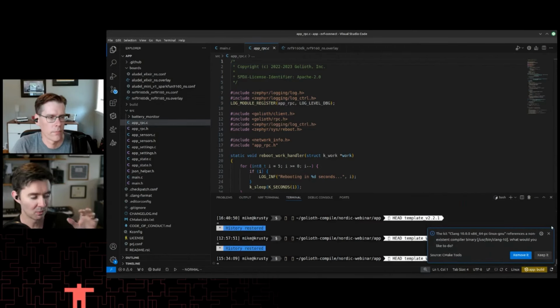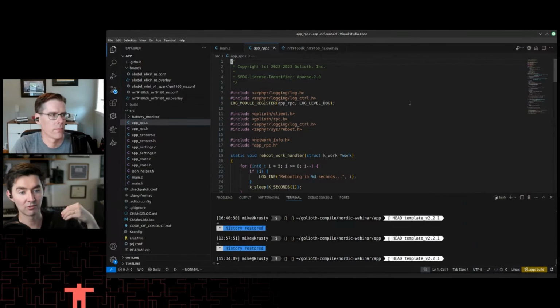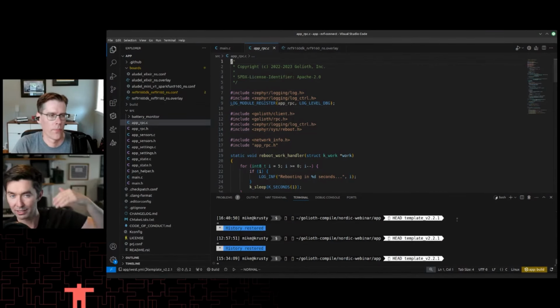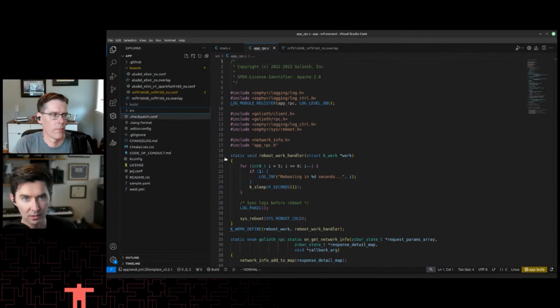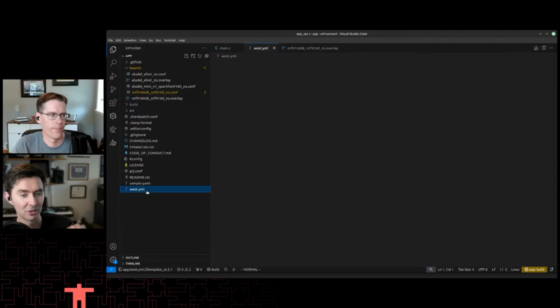Ultimately, we do that as a dependency so that if Mike hands me a project and all the code that's in it, I can actually just do a west init with the manifest that's tied to that project. And ultimately, it'll pull in all the dependencies, including Zephyr, tagged to a very specific version. When we think about how we expect people to be working in a production environment with multiple teams, you don't want Zephyr or NCS in your repository. You don't want someone fiddling around with NCS in the background and then you break your build for some reason. You want to have a very well-known version, and treating it as a dependency really helps that.